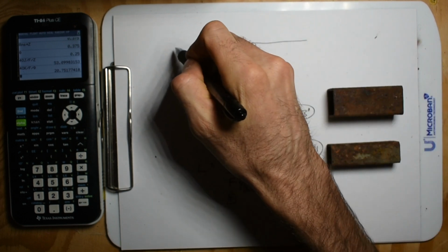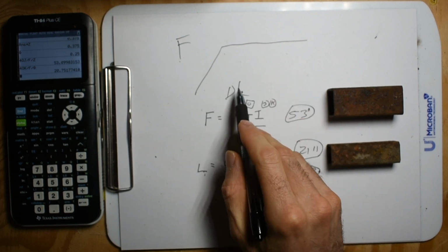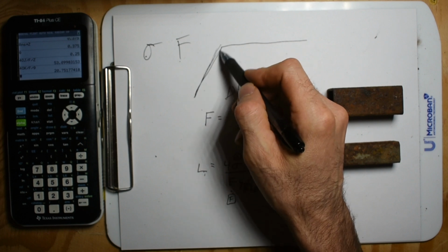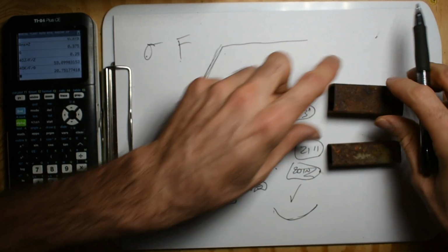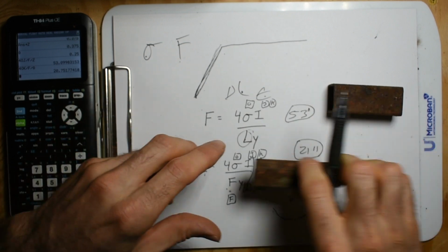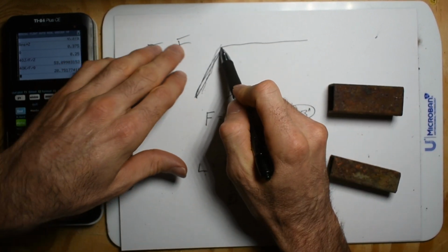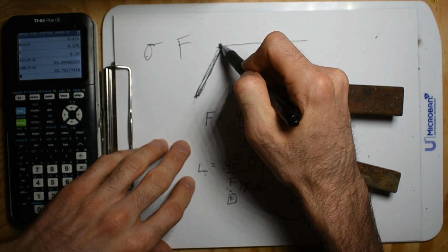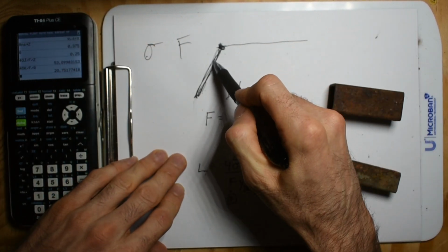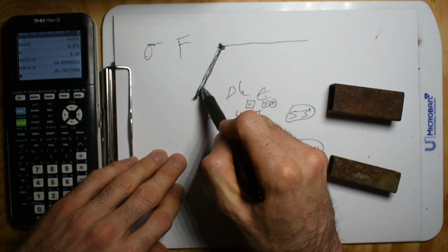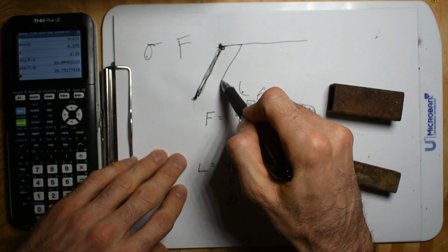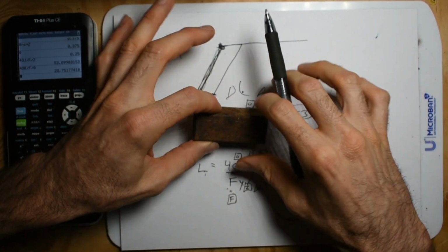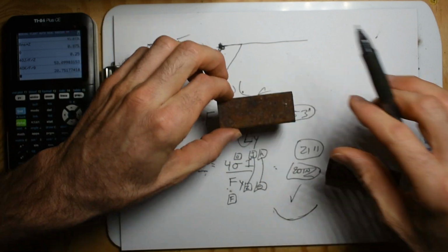We have this force versus change in length curve, or stress-strain curve, and we want to operate in here. Things are going to bend a little bit. We are going to lengthen things when we tug on them, when we apply the max force. But as long as we stay within this line, when we let go of the force, when I step off this, every molecule will go back to the same location. You put more than that, and then we get a permanent change, it's permanently stretched by this much. It's permanently deformed. Now it looks like a smiley face.